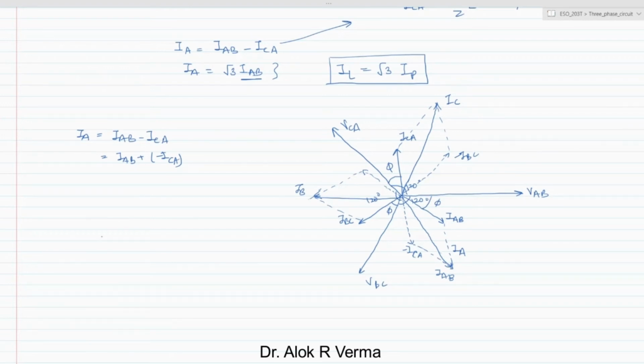Is it okay? So this is the balanced load which is connected for delta connection with the supply. So this is how we are going to be dealing with it. Now in case of unbalanced supply, the angles will change, but the philosophy will remain same. The angle phi will be different in case of unbalanced load, or the magnitude of Z per phase will be different,